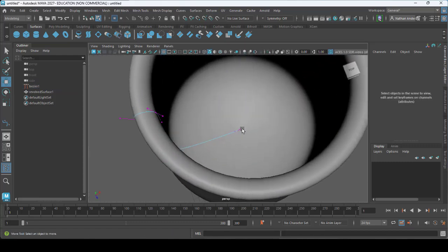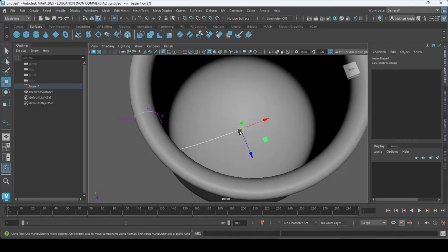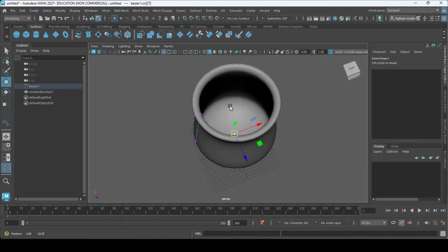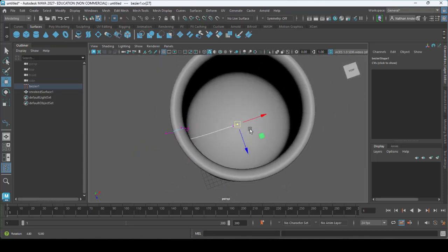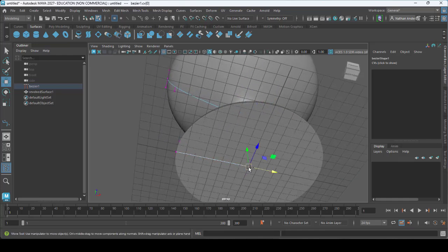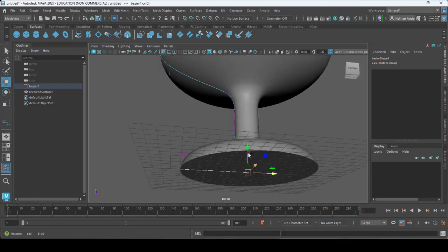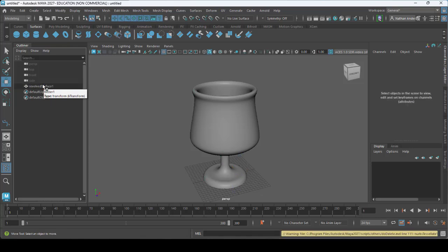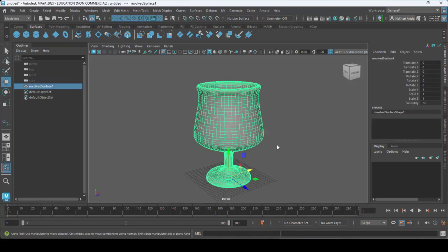Another point to mention is that if you don't perfectly center the point where the curve terminates, it will create holes in your topology. That was one of the reasons why I centered these vertices at the beginning and end of the curve when I created this. And again, I would just press the X button, and that lets you snap it to the grid. Once you're done, you can delete the curve, and that leaves you with just the 3D object. All right, why don't you give that a try and move on to the next lesson.